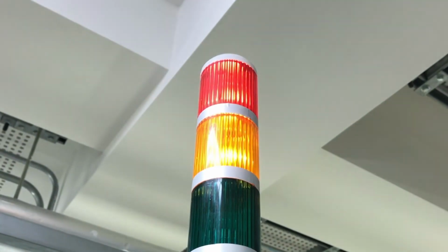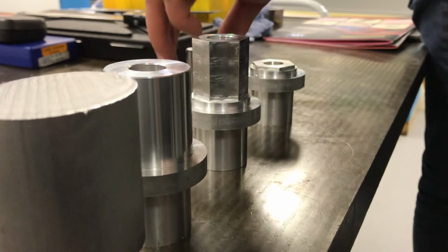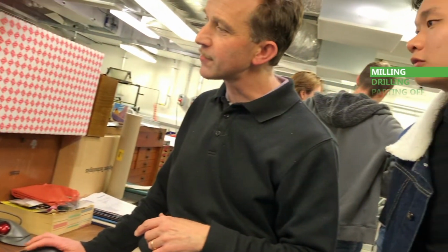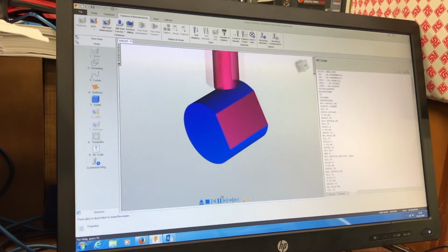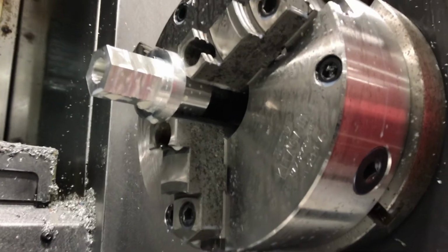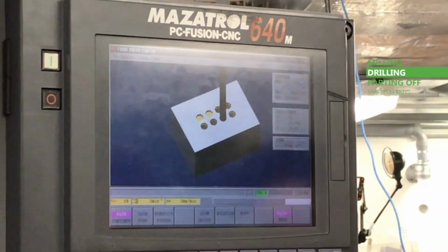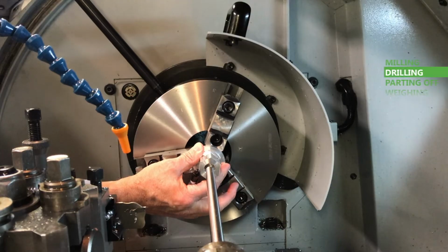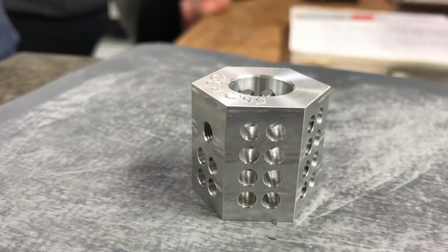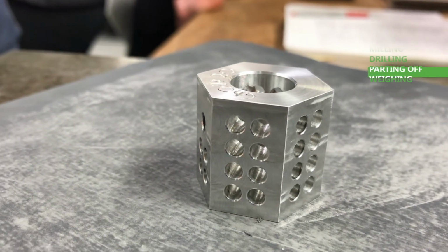So now we embarked on our corrected manufacturing journey, beginning with the hub. Using a CNC machine, our hub was manufactured from a section of solid circular aluminium. The hexagonal sides were milled to shape, and then the holes we included to reduce the weight were also quickly done. The hub was then parted off with a lathe, and we made sure that the hub stayed within the weight limit. In fact, there was a 10-gram reduction in weight compared to the other groups due to the holes we drilled.